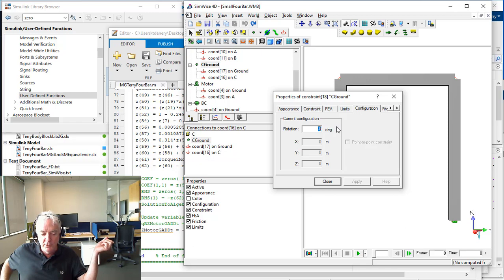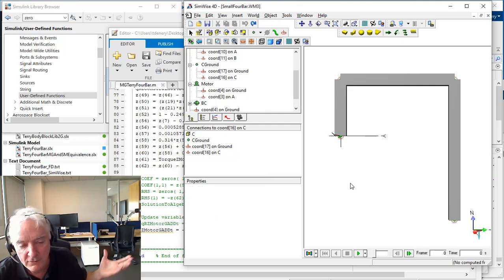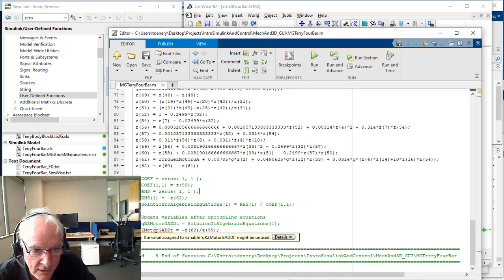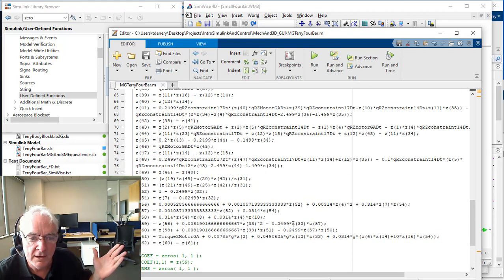In general, I define a nominal configuration or positioning for all of my mechanical assemblies, and I always, in nominal configuration, set my initial condition to 0. For that reason, quite often, for things I do using integrator blocks, the default initial condition of 0 generally works for me. So anyways, as we go through this, I think you'll see why this is important and why the solution is going to be composed the way it is.